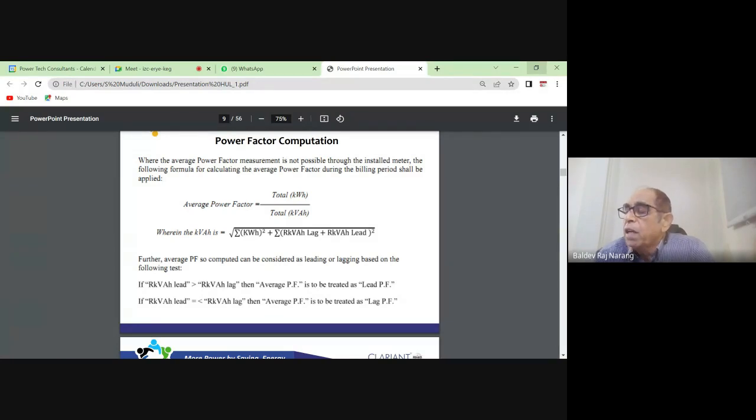So earlier, initially, the reactive power was coming free. People were just maintaining 0.9 power factor and getting away with that. Then the utilities thought, because their system was being underutilized, that if we have 0.9 power factor, 10% of the system remains unutilized. Their installation is for 100%. The currents, people at 0.9 itself, they draw the full load current.